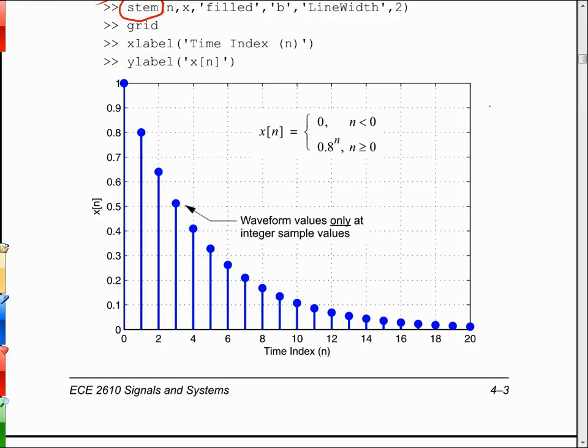Don't know the proprietary part of it, but the accelerometer is part of the main key in deciding if the airbags are going to blow or not. So there's got to be some very significant decision making done based on the waveform that gets sensed by that accelerometer, and it's done as a digital filter and then processed and compared against a threshold.